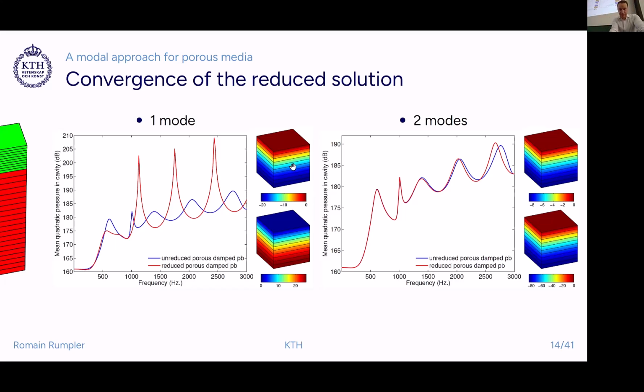And what do we see here? Well, we see the first mode looks like antiphase, with fairly the same scaling of the two phases. And then for the second one, top is the solid phase, bottom is the fluid phase, and you have the relative scaling between the two thanks to the scale that we have here. For the second one, you can see a ratio of about 1 to 10 between the solid and the fluid phase, which are actually, for this mode, in phase.